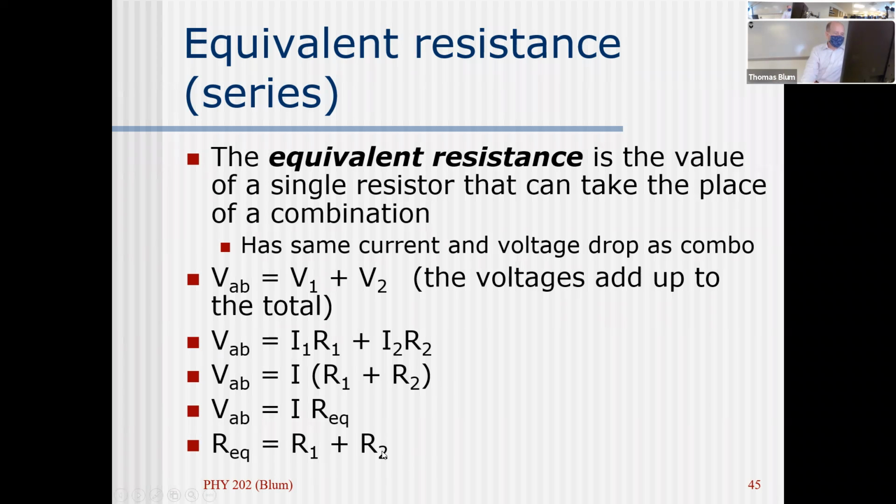So there, that's what we have. That is the concept of equivalent resistance. I can replace two resistors with one that will have the same effect, the same voltage giving me the same current. That's what I mean by the same effect. So I'm going to replace two with one, but the resistance must change. And what must the resistance be? R1 plus R2.